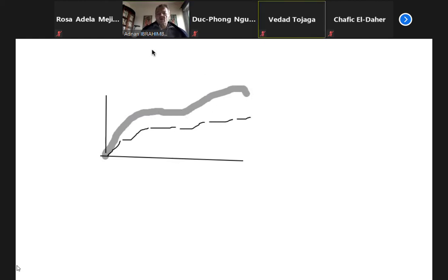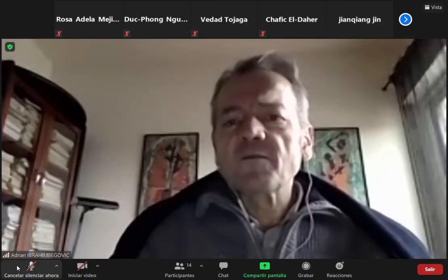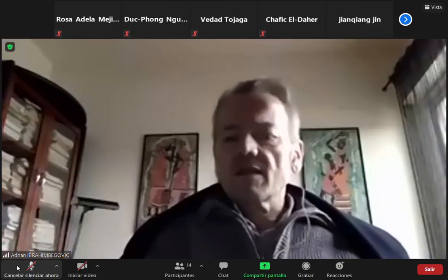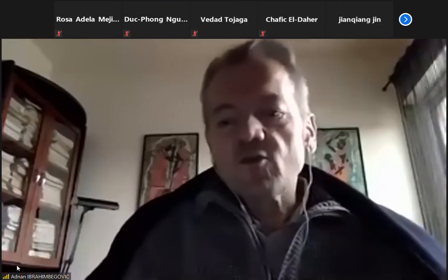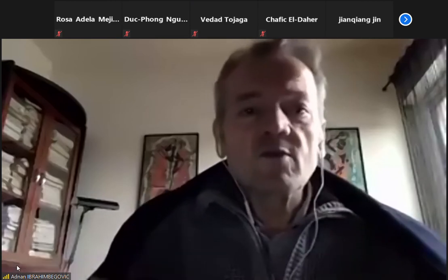So here, when you unload from here, this is your plastic deformation. When you unload from here, this is your plastic deformation. So see, it looks better, but it could have looked worse, because here you get even more plastic deformation. It all depends on what you want. I'm saying that in all these situations, it's very important to be able to converge down to a residual which is small enough.